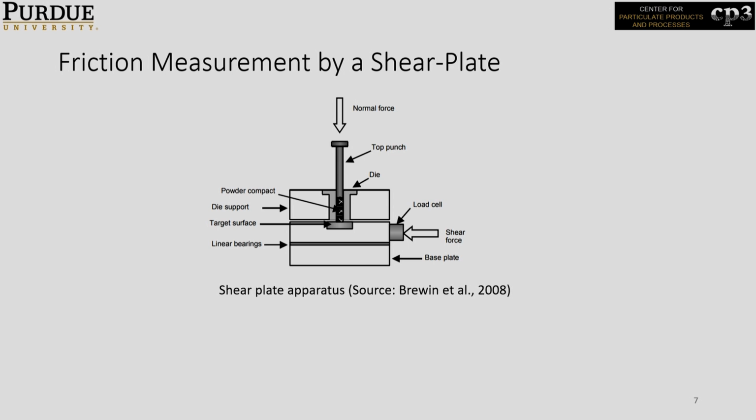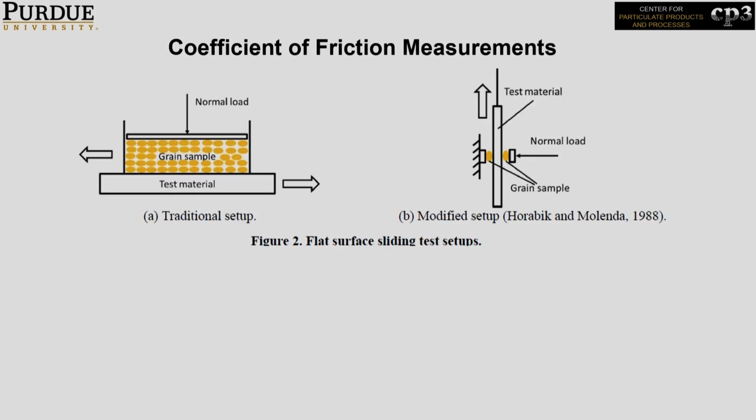Okay, and then again you get the forces acting between those plates. And the same disadvantage can happen here, by the rolling of the material inside. So if it rolls, then your accuracy goes down. Or the old setup that I talked about using Instron, you can move both the surfaces. So you can avoid a little bit of the rolling effect here if you're moving both of those across, but still, it's not a very accurate method.